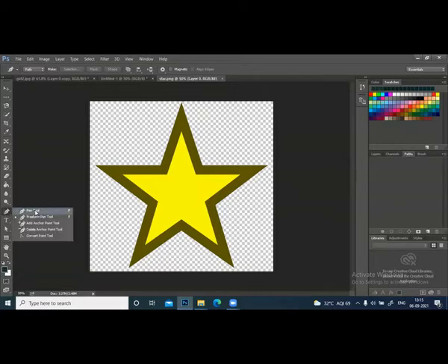So I'll go to the pen tool, select the pen, first point, second, third, fourth, fifth, sixth, seventh. When you are reaching the start, it will show a small circle. Close it. I want to make some changes because you see this point is a little far away.